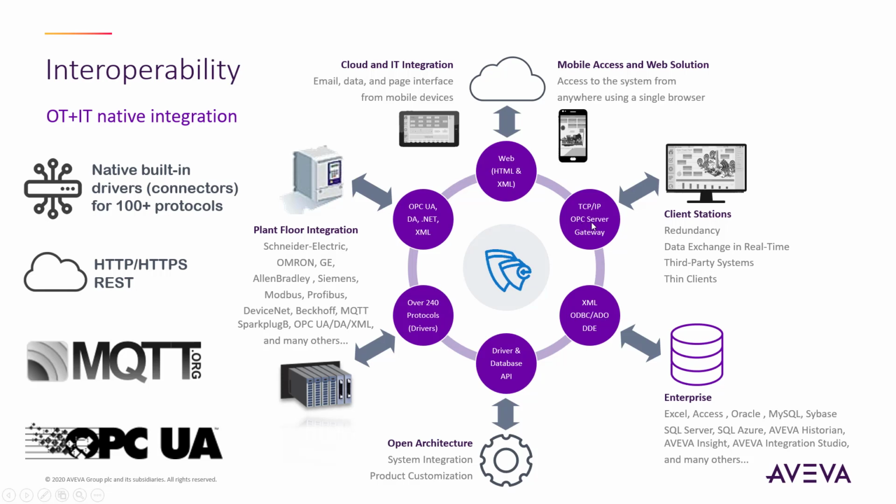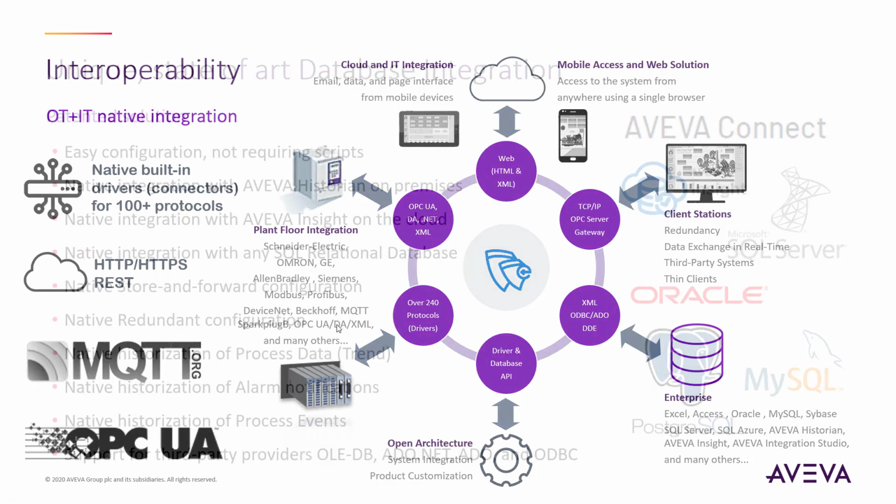Now, acting as an OPC server, picture this: we can be a server to anybody's third-party client. They could talk to our OPC server and then get to any of our drivers. So we can be an OPC server talking to PLCs very, very cost effectively.